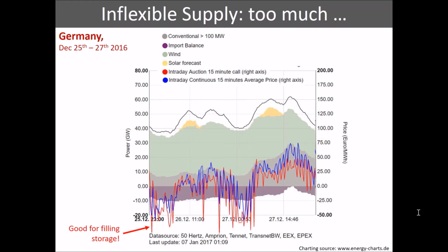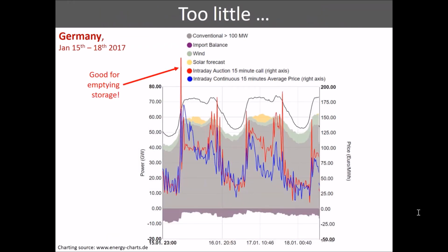It's also important to note that when we think about putting more renewables into a system, people often focus on, well, what happens when the wind's not blowing or the sun's not shining, will the lights go out? Actually, this issue of oversupply is likely to be as big going forwards, and growing, as the issue of undersupply. And that's again down to the low capacity factor of the sources that we're building. To create the same amount of energy over time, we have to build an awful lot more solar and an awful lot more wind than with some of the previous conventional resources. So we're going to have to get used to these situations where we have too much supply at times of low demand.